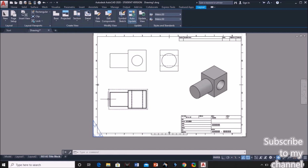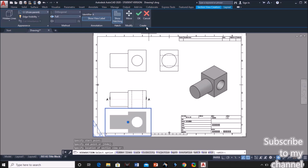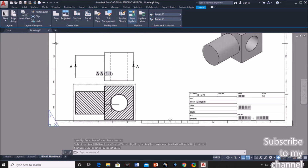So I need to make a sectional view for this object. Go to sectional, select any one of these options, select the full section. Now select one view, specify first point and specify other point, just drag to the other side and click the position. Next, after this, click on OK.